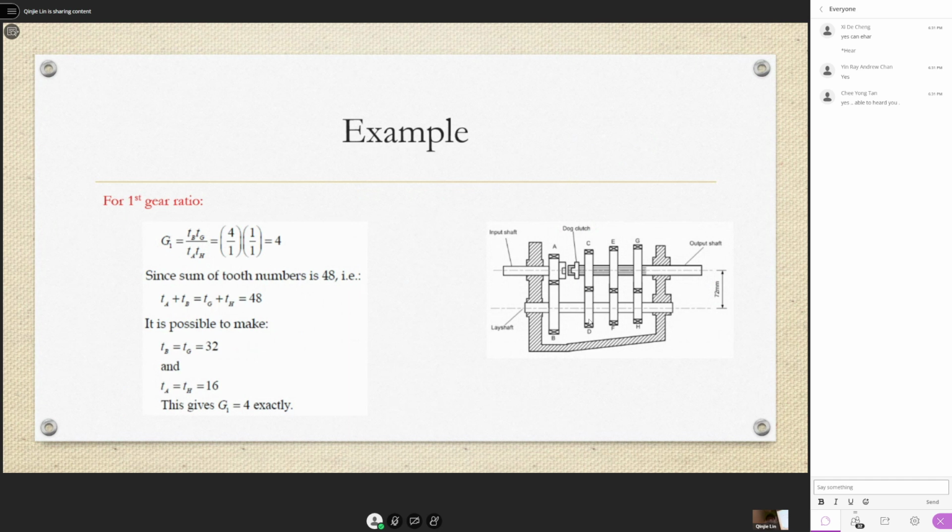So for the first gear, they tell you they want an output gear ratio of 4. Okay, so from this gear A all the way until the end, down here they use G and H to illustrate the first gear. So A will transmit to B, then B in turn will cause H to turn. H is connected to G and then will cause G to turn. So the total gear ratio for this system is actually B over A to describe the first part.